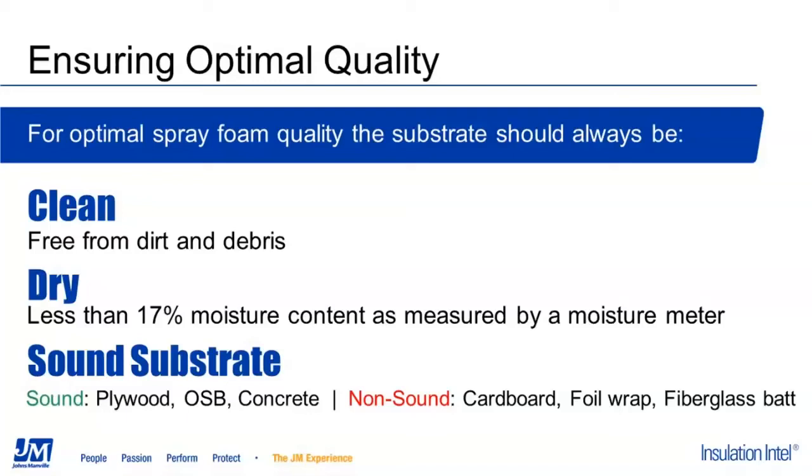After the proper substrate has been selected and prior to the installation of spray foam, the installer needs to check that the substrate is free of dirt and debris and contains less than 17% moisture content as measured by a moisture meter, as both can lead to adhesion issues.